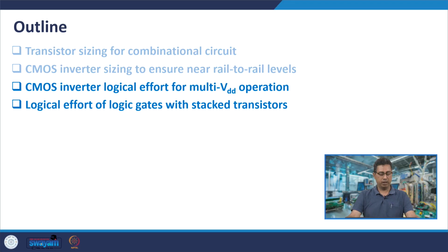So, we will first discuss the charging and discharging mechanism of near threshold voltage circuits, particularly logic gates which have stacked transistors, and then we will discuss a very simple method to obtain an approximate value of logical effort of these near threshold logic gates, and then we will discuss the logic path sizing, transistor sizing in logic path using this modified logical effort method.